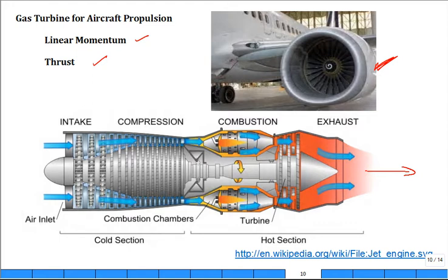So basically here we have an air inlet through a compressor. Notice this getting smaller, higher pressure. Then it goes through the combustor. Not all the gas goes through into the combustor. A lot of it helps center the flame, and then it's mixed, and so it's lower temperature when it goes through the turbine section. The turbine section produces just enough power to run the compressor. There's no shaft feeding out, right?